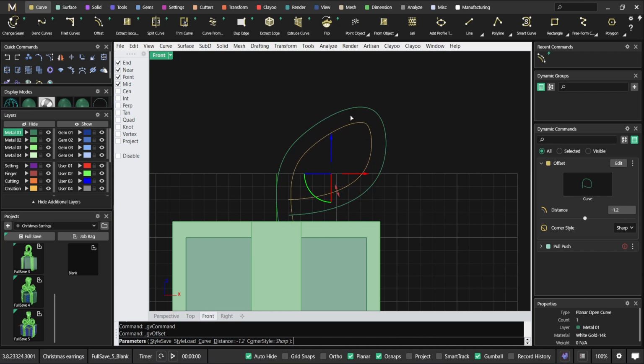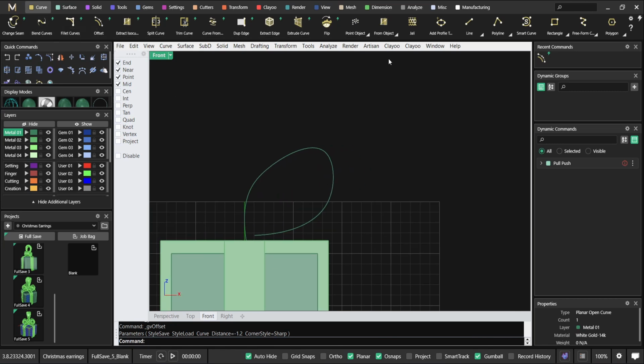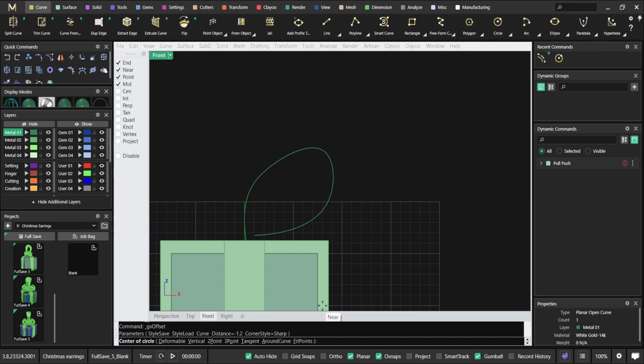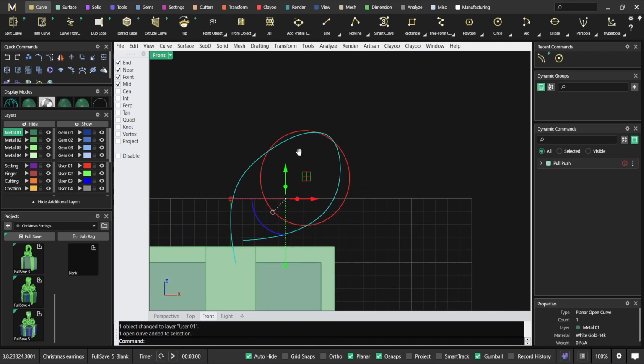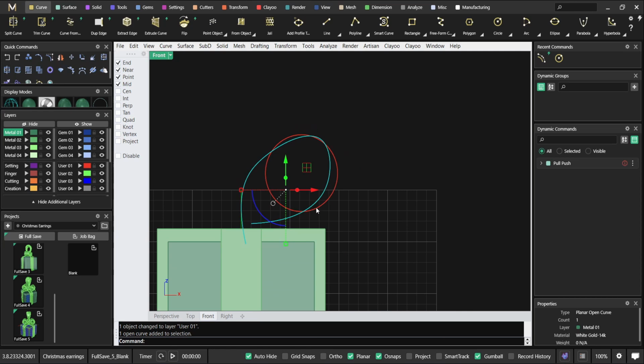But before I do that, I want to make sure that the outside line is completely, it's a bit more rounded than what it is now. So as you can see, it's not fully rounded. So it's going to look much better if I make it a bit rounded. So one little tip is to use a circle just as a visual reference. I'm not going to use this circle. Okay. So 3 points, and then just draw a circle around here. You can put it in another layer if you want to. And now you can edit this line to make sure it follows this curvature.